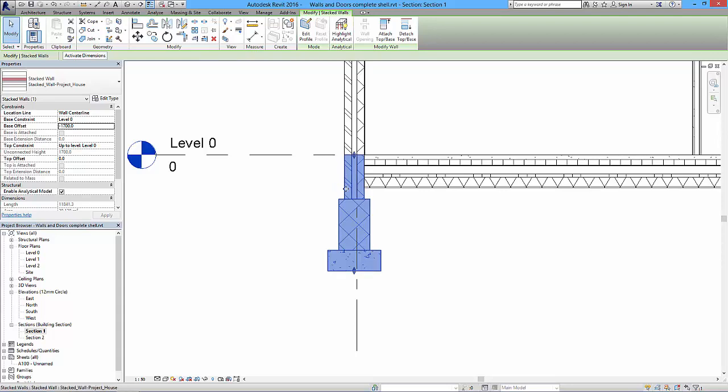Then you want to make sure that you've got enough facing brick to cover up any sort of change in level round about this height. So that's why we've extended it down a little bit further. Also, it allows us to hardcore the ground to above the foundation block as well. And it looks a bit neater in this instance.